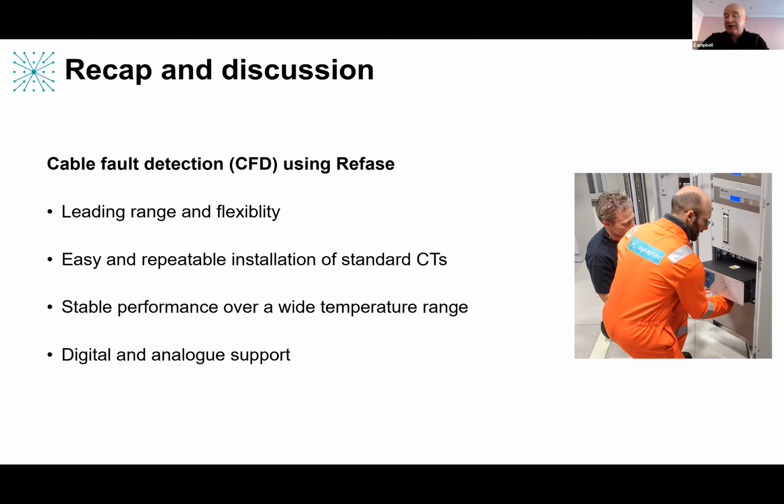To be honest, that's something that we're not looking at in great detail, and it's not really the focus of today. And Philip, please feel free to come in, but the exact identification of where the fault is, down to meter resolution, is not something that we are focused on at the moment. It's more the section, whether it's overhead or underground, and if it's underground, which section it is on, and therefore you would inhibit the auto reclose. I think that's the major driver behind what we're doing now. But if you have distributed measurements, of course, there are other things that you could do, and the precise fault location, as opposed to faulted section identification, is something that we're looking at, but I don't think we've got anything that we can say that we're doing right now.